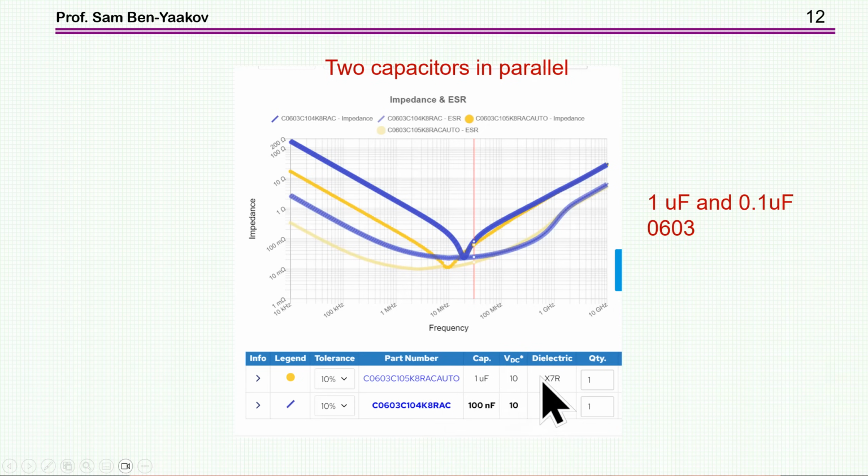Both are X7R and both have the same package. So I'm putting these in parallel, and hopefully, as the common wisdom says, put 0.1 microfarad.